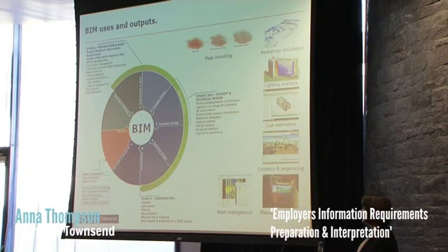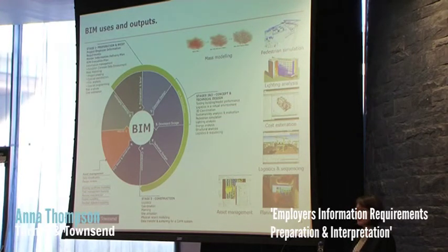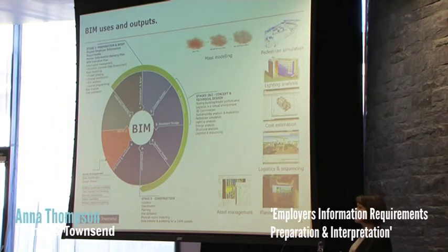But for a client, they may not all drive value and efficiency and meet the client's objectives. So we need to think about which of these BIM uses drives the most value for our client, and we need to define them in the EIR document. So do we want to see the models being able to be used for cost estimation and management? Do we want to see the models being used for coordination and sequencing? So testing in a virtual environment, those time solutions to come up with the optimum program and time solution. Does the client want to use the model for asset management? If they don't, there's no point in making sure lots of information goes into the model if it's not going to be worthwhile.